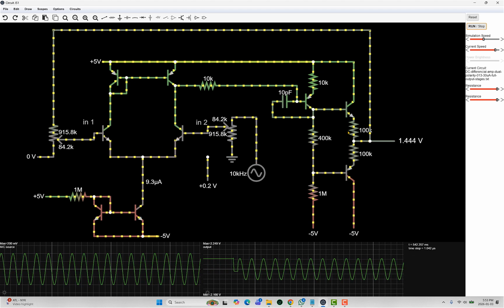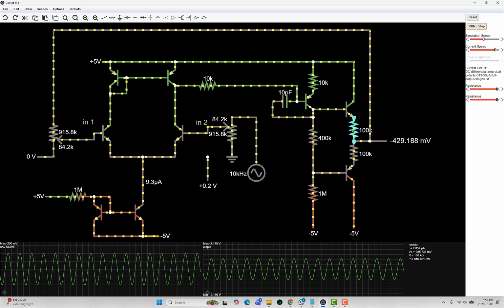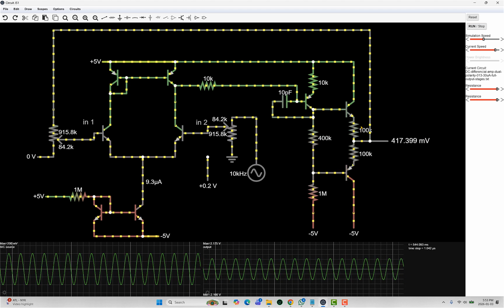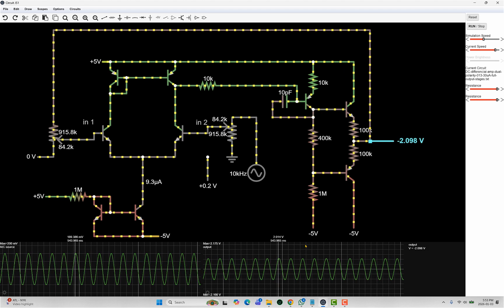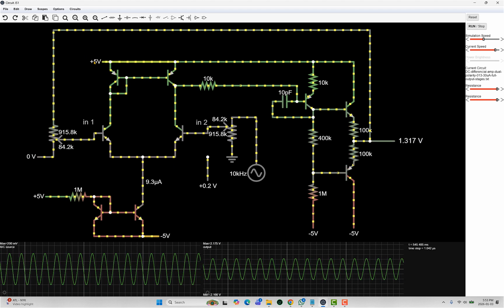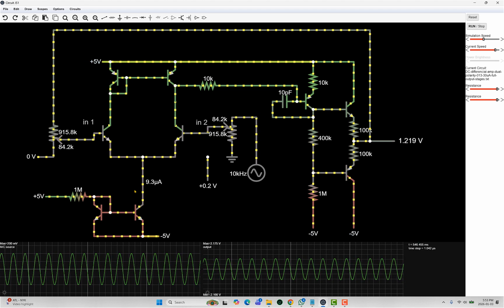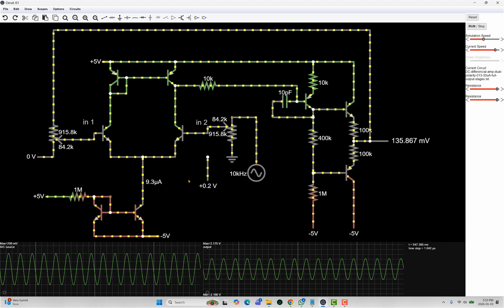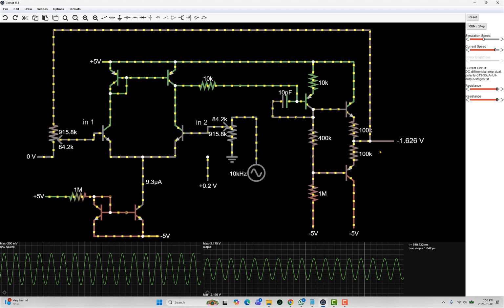And you'll see I've got these resistors kind of high, but they can be lower. Okay, because I'll show you. So if you need a lower source impedance, you're driving something, 100K is pretty high. The reason I left them at 100K is it draws less power for this whole circuit, right? And I've got it biased at +5 and -5. Okay, there's my little current source for the input stage, which is a differential amplifier.